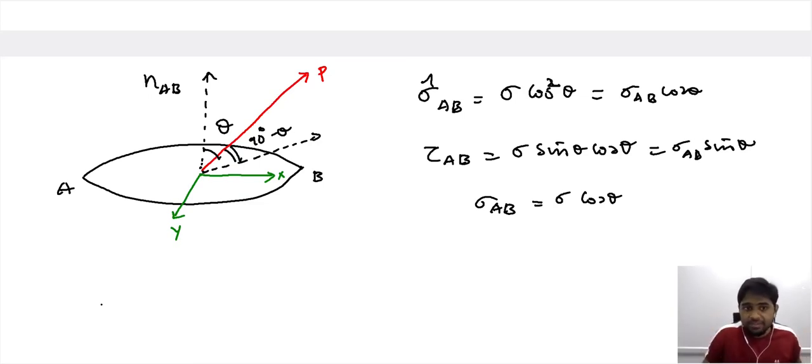Now what essentially we have done is, the answer that we have is only for this direction, that is with respect to 90 minus theta. That is the only solution that we have right now. However, what we need is a generalized solution that can be used to describe the stress acting on the surface of AB along any direction. Now we are confined to only one direction because our understanding comes from a pseudo 3-dimensional consideration. So therefore what we need is a generalized expression which can be used to describe stress along any direction. So therefore we introduce this coordinate system.